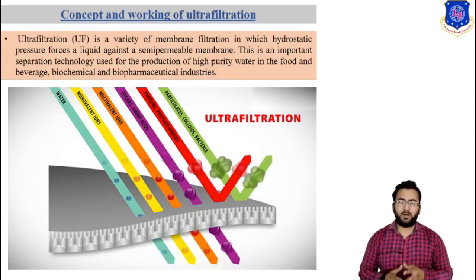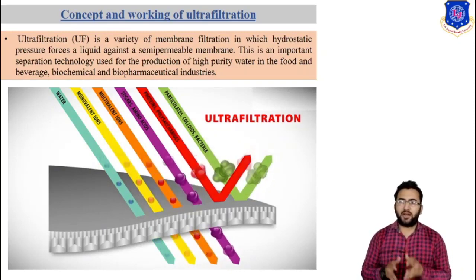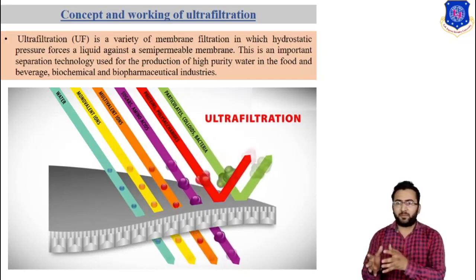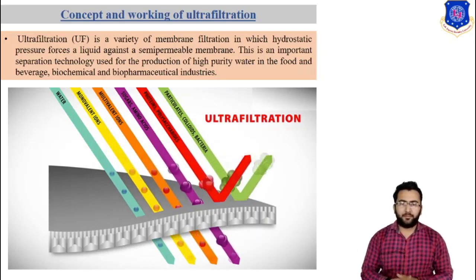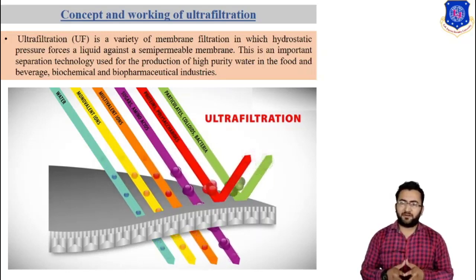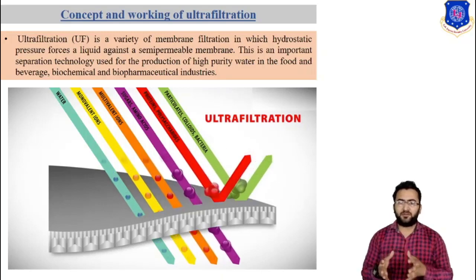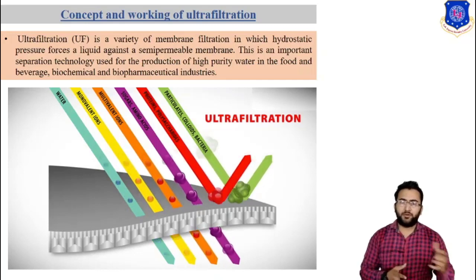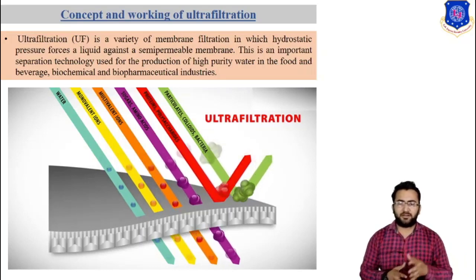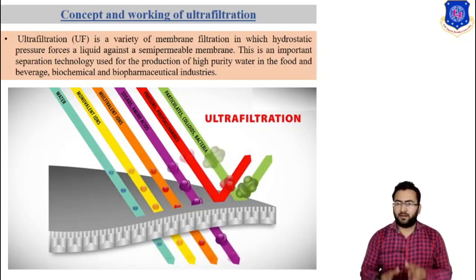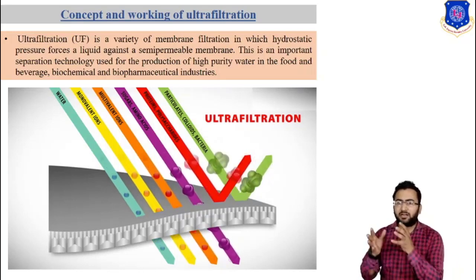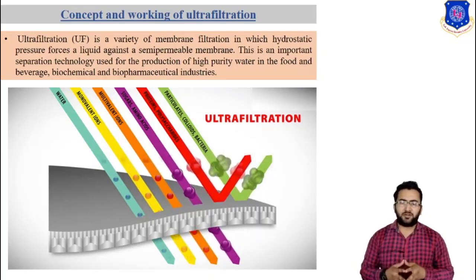Bechhold introduced the term ultrafiltration, forcing solution at pressure up to several atmospheres through a membrane prepared by immersing filter paper in acetic acid colloid. Ultrafiltration is a variety of membrane filtration in which hydrostatic pressure forces a liquid against a semi-permeable membrane. This is an important separation technology used for the production of pure water in the beverage and food industry, biochemical industry and biopharmaceutical industry. Ultrafiltration has a unique ability to purify, separate and concentrate targeted macromolecules in a continuous system.